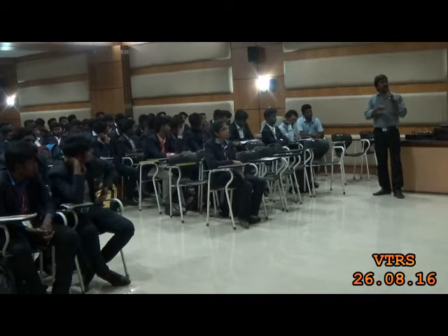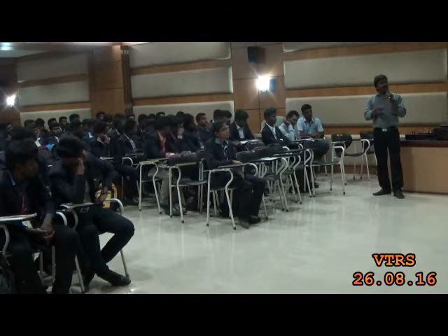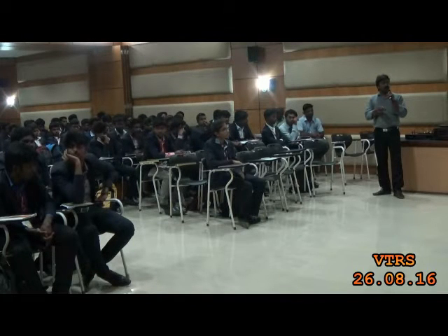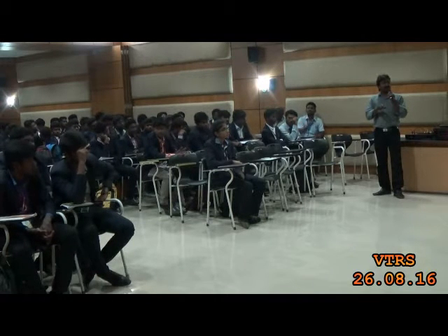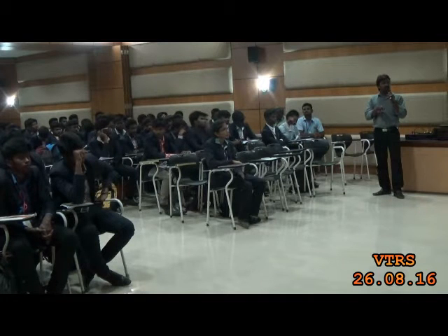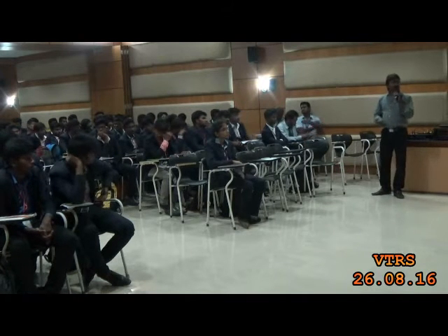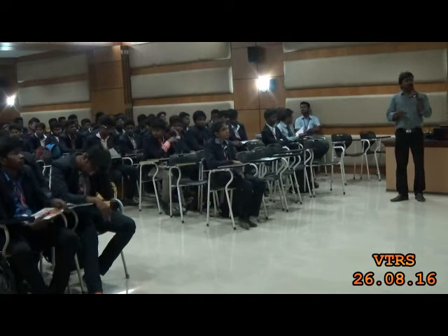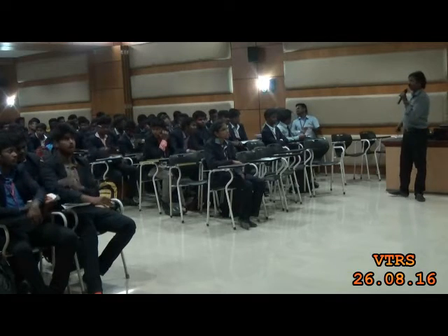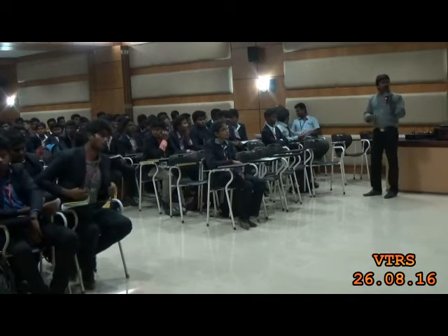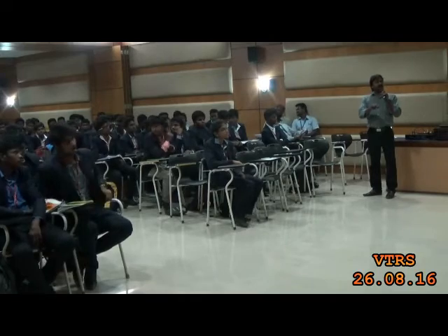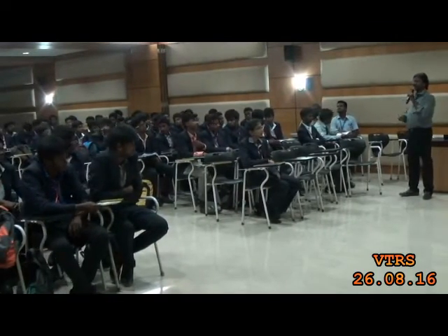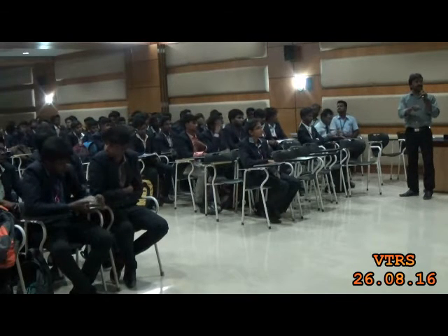So this is the crank pin end. If its length is L2, its diameter is D2, and its pressure on the pin is Pb2, the load on the pin can be calculated similarly to the earlier one, like Pb2 into D2 into L2. And the outer diameter can similarly be calculated by D2 plus 2 into the bush thickness plus 2 into marginal thickness. So your output will be what? You will be getting the dimensions of your piston pin end and crank pin end, and you can arrive at this design of the connecting rod.